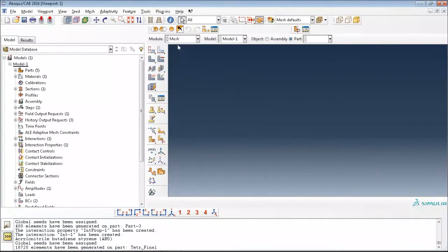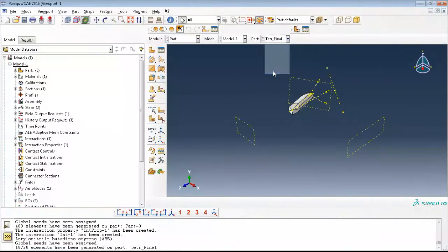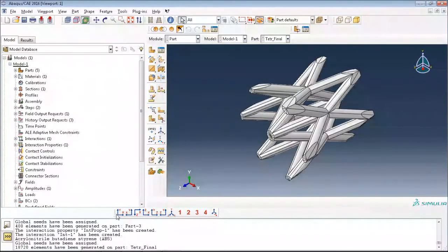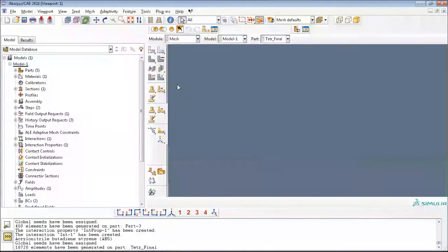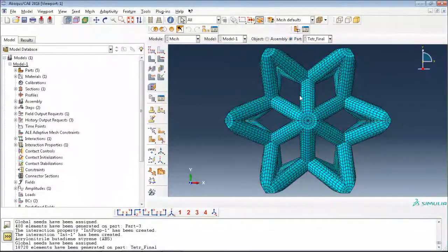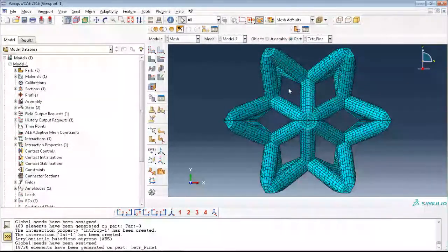So now, see, it's very quick. We got all this configuration under the boundary condition. I will go to see how this part looks like, how this one looks for tetrahedron parts. This one, the unit cell, as you see, is distributed in one radial level. And this one is partitioned, and you can see here the mesh. We could apply the hexahedral mesh, which is brick elements. This element is a very efficient element for capturing the post-yield and fracture criteria.